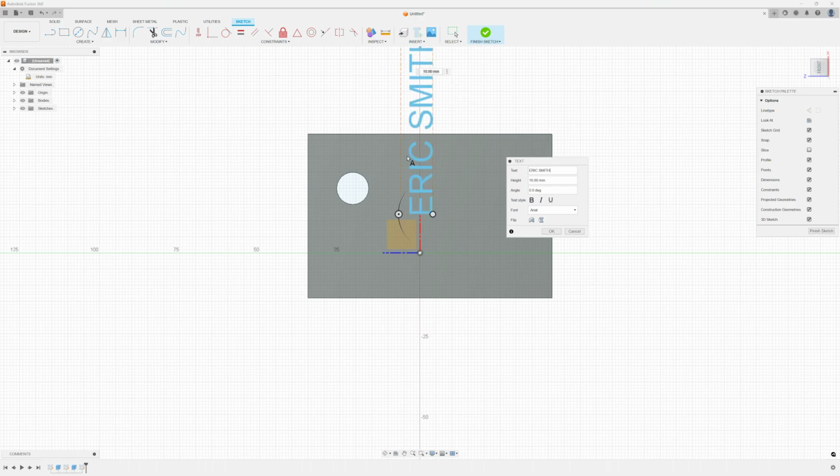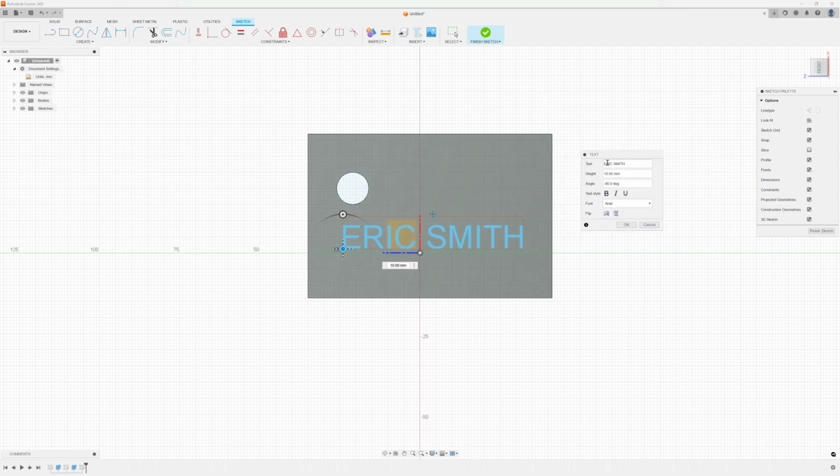and well, look at that. I made the text in that direction. I don't want that. Everything has a nice little handle, so just grab it and turn it. I can grab the middle here and move it. And maybe the text is too big, so I'll come over here. I don't want the text so big, so I'll left click on all this and type maybe 6 mm. Maybe I want it to be a little bit fatter, so I'll click the bold and I'll click OK.